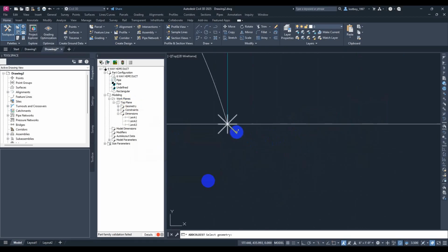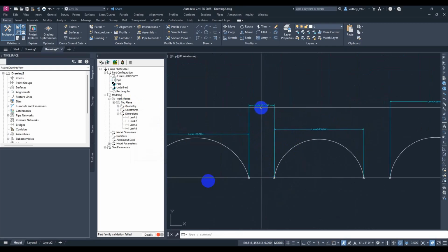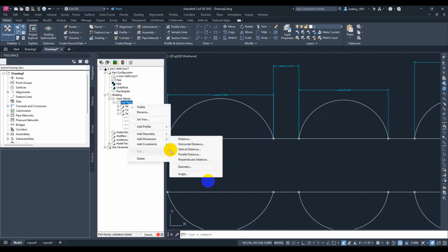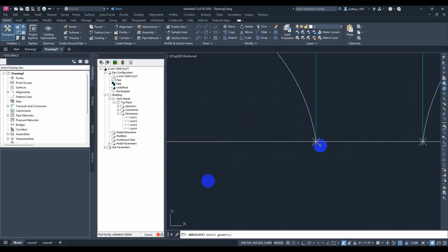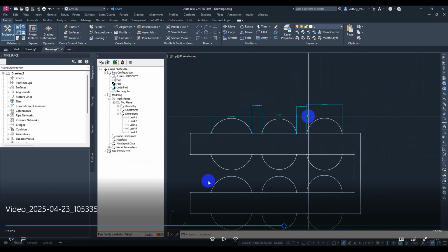Okay, now you will give also the distance between the pipes, a dimension. This dimension also is very important in the modeling to give the spaces between the pipes later. I haven't tried this, but you can try. And we could not add this dimension. We could make the spaces between 2 points here equal to this one and give only one dimension. And this one dimension will control the space between all the pipes. So I haven't tried this, but you can try, but I think it will work.